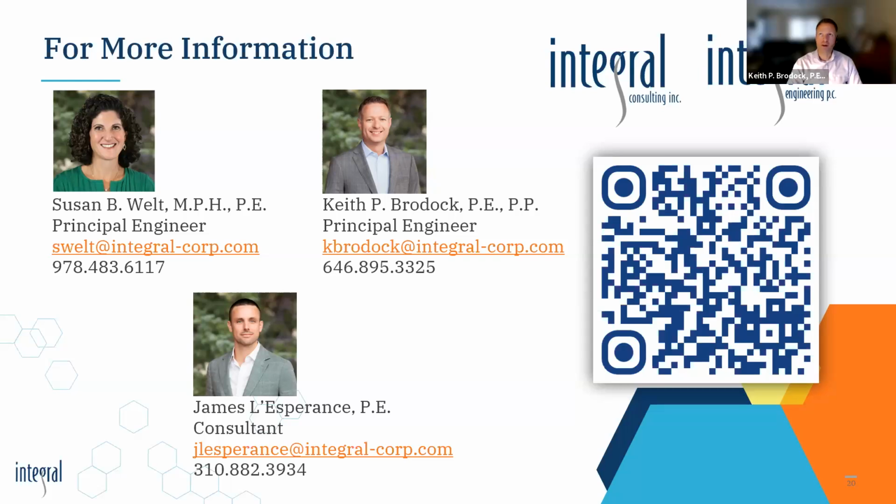And one other thing that comes to mind is while we're there doing the work for the investigation, we're also looking at the building, right? How's their HVAC system designed? Does it bring in fresh air? Is there a chance that we could positively pressurize the space with existing equipment? Whether or not we identify that vapor intrusion risk or issue that needs to be mitigated as part of our investigation, we're already thinking ahead to the solutions.